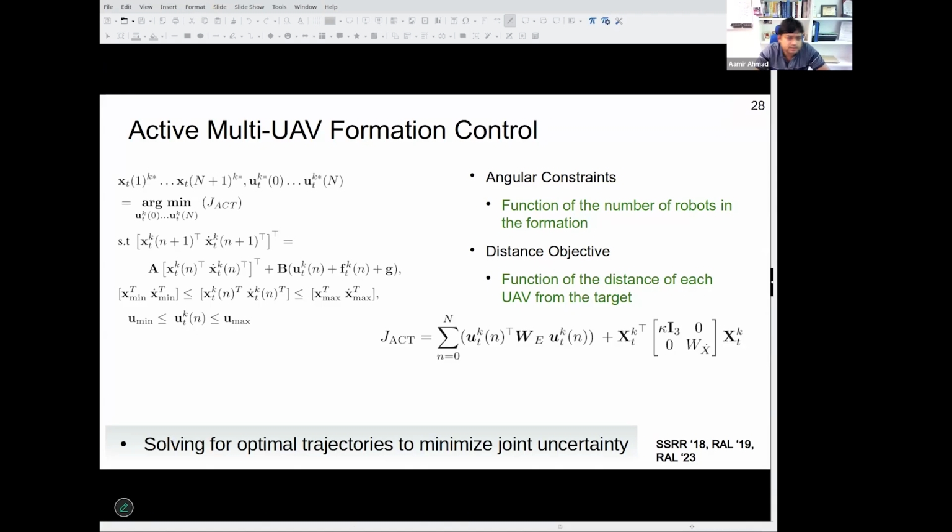The idea in this MPC is to model the UAV as a linear system, and the dynamics are one of the constraints. So the linear system dynamics, and the other constraints are the limits of the state and control actions and so on. The output of the MPC is then the trajectory of waypoints and velocities that are provided as a reference to the low-level waypoint controller, right? For a multi-rotor drone, you can achieve a much faster inner loop control.